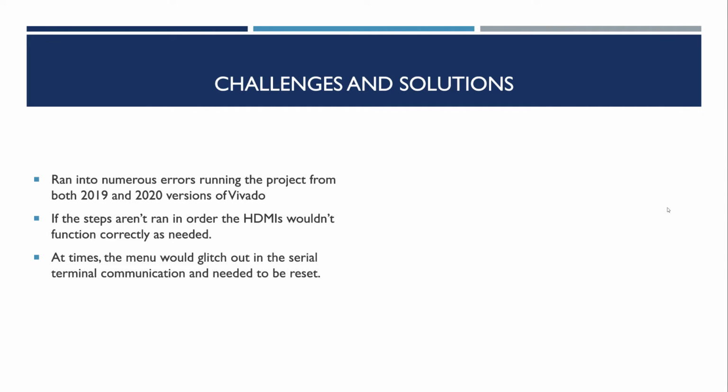This helped me, because even though I updated the IPs and everything in the other Vivado versions, it still wouldn't fully function, and I would still get errors when I would run the implementation and stuff like that. So going back to a different version of Vivado helped. And I saw in the forum that the moderators from Xilinx recommended going back a couple versions.